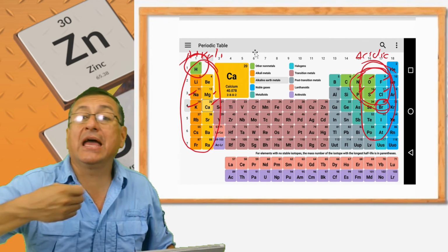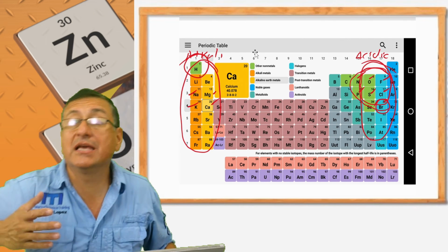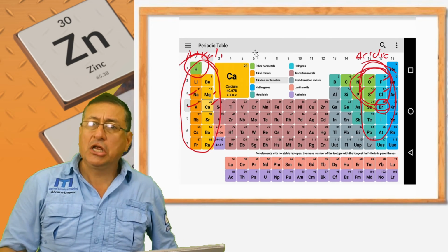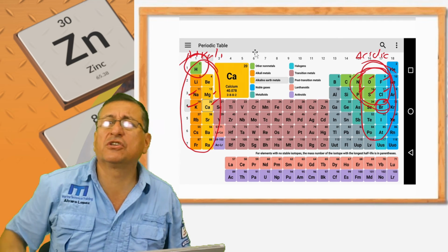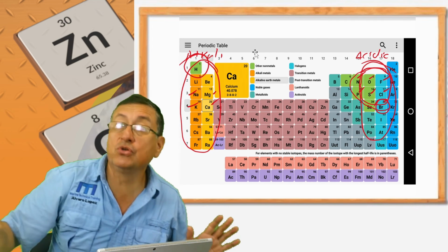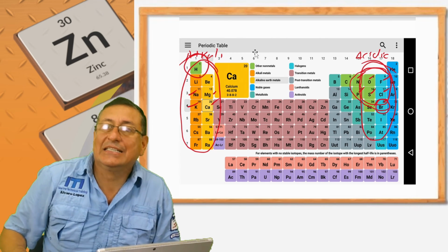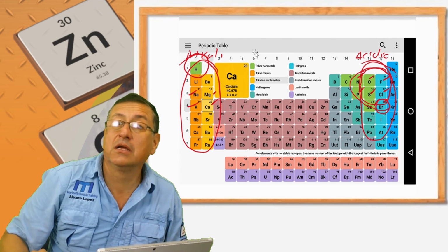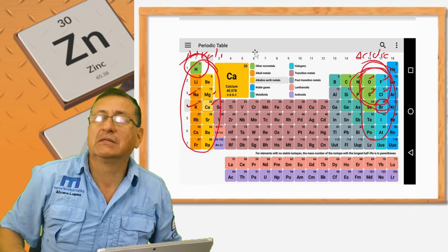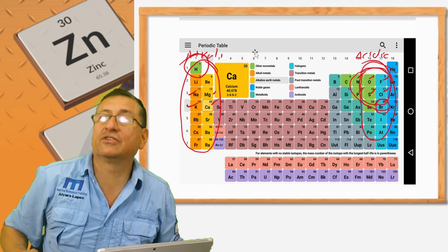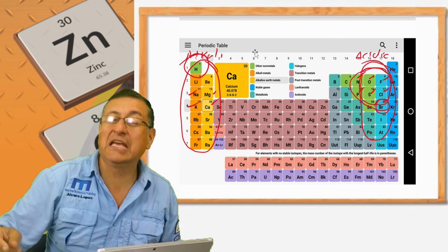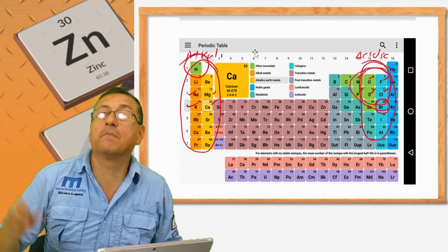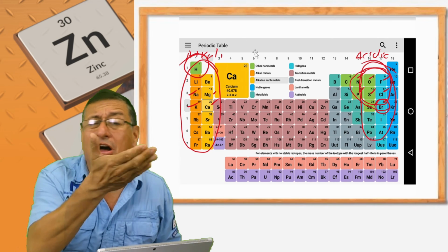When you apply paint improperly on the surface of your material, on the surface of your hull. No, I painted the hull with the paint that I have in the storage of my home, and now the hull looks nice. Yeah, looks nice, but this is not appropriate for a marine environment. You want to put the boat in the water tomorrow? Yes, tomorrow morning I'm going to put the boat in. Oh, baby, that coating will be catastrophic for your boat. This is organic, it's not marine approved. The color is nice, but this is not a bottom paint, and it's not appropriate for that hull in aluminum.